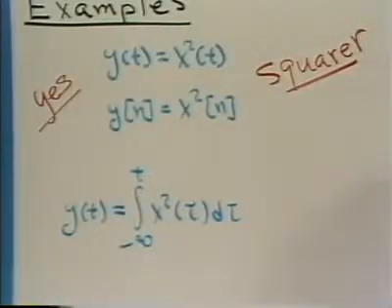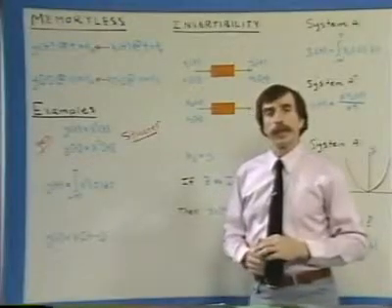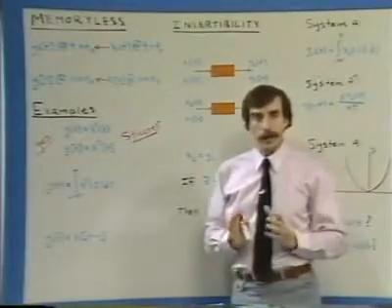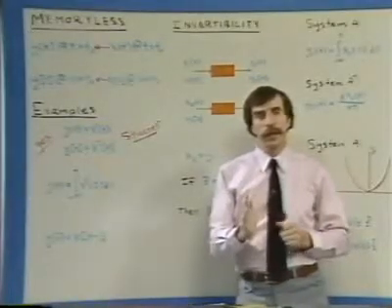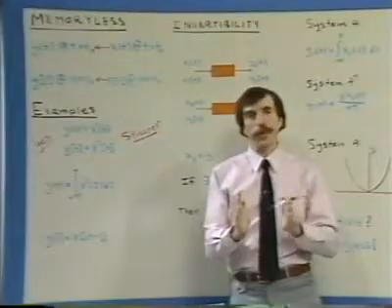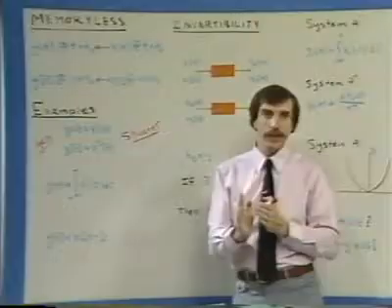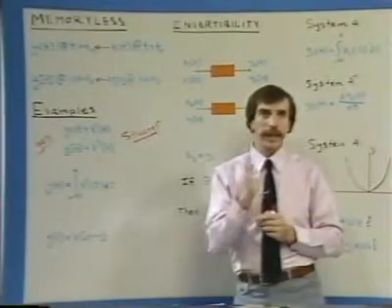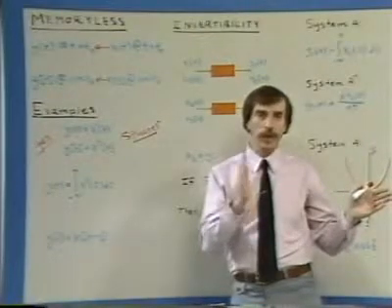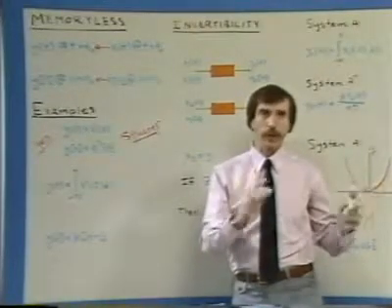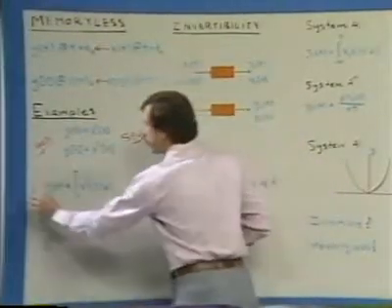And whether we square before we integrate or not, the essential point is that since we're integrating the input, the value of the output at any time is an accumulation of past history of the input. Well, an accumulation of past history in essence implies memory. To get the output at a given time requires the input over an interval, specifically for longer than that time. So this system, in fact, is not memoryless.